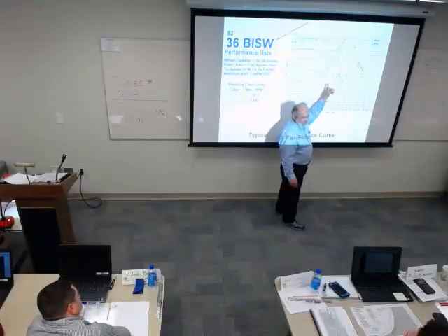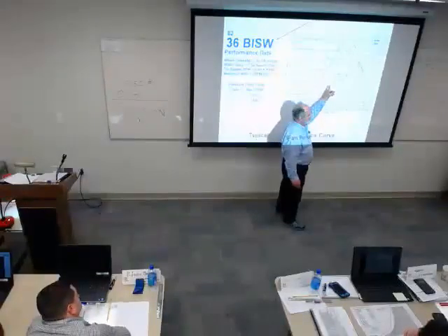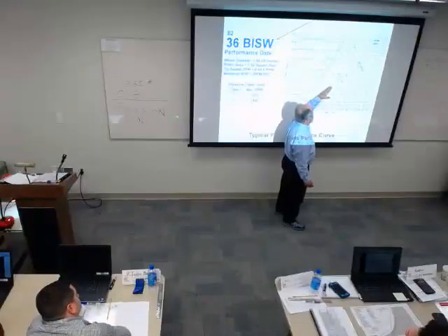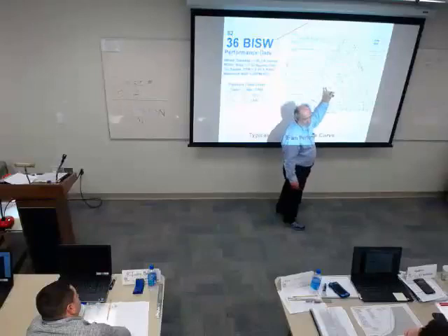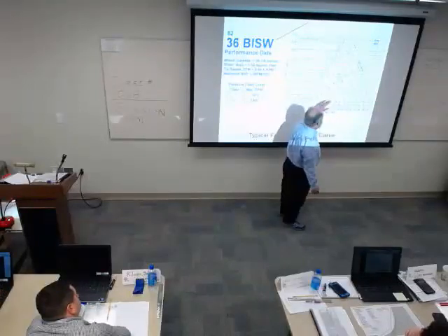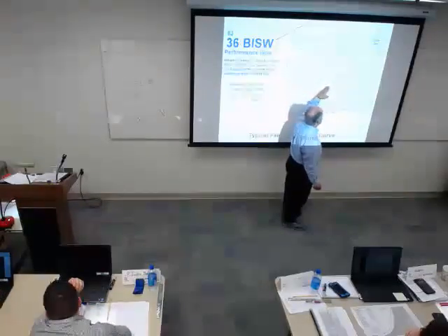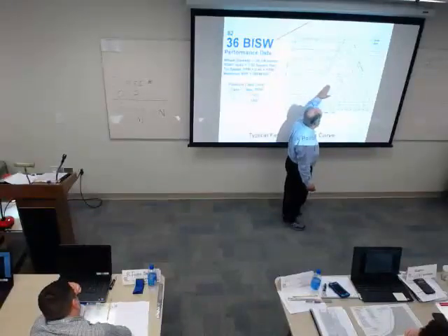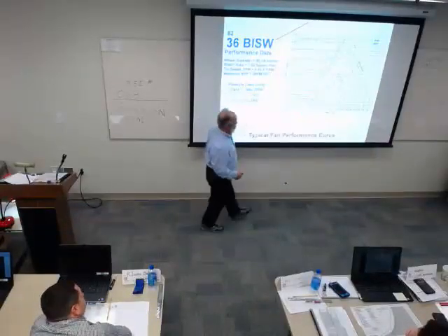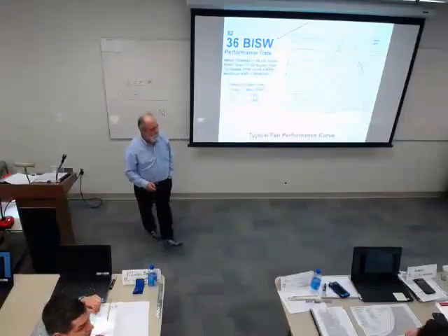In the design, we really highly recommend you stay away from that knee. When you do test and balance or install the plant, it's not unusual to have to speed the fan up, and if you're too close to that knee, you're over here in no time flat. So fans should be selected down on this part of the curve. So what causes that?